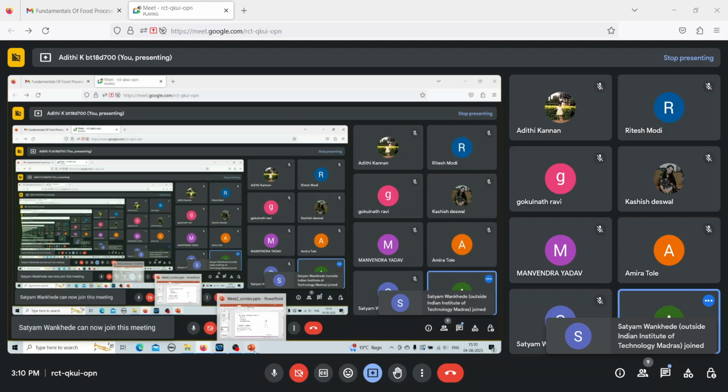I'll tell you what is what here. Epsilon is the strain, sigma is the stress, capital E is the Young's modulus of elasticity for the springs, lambda retardation is the retardation time, and mu is the viscosity of the fluid present in the dashpot.